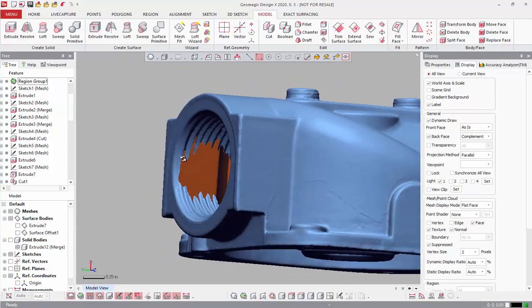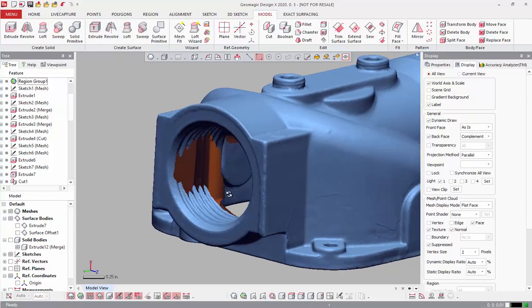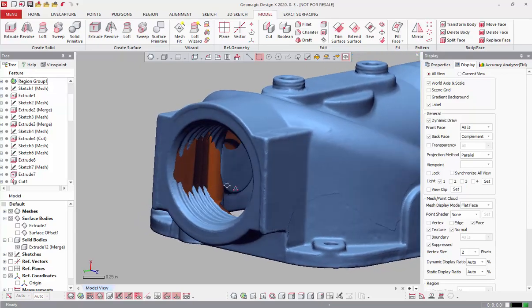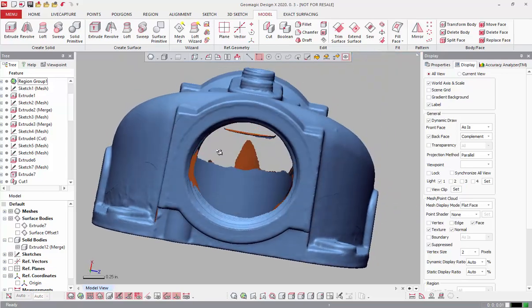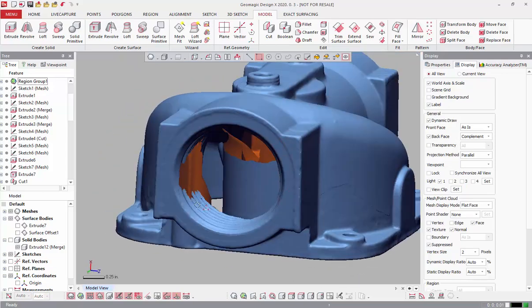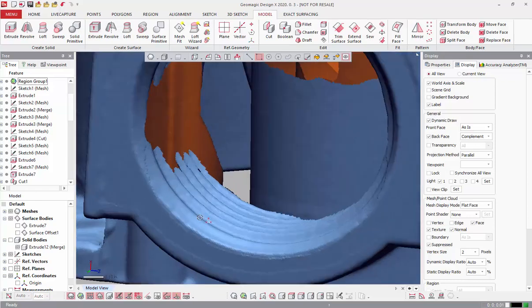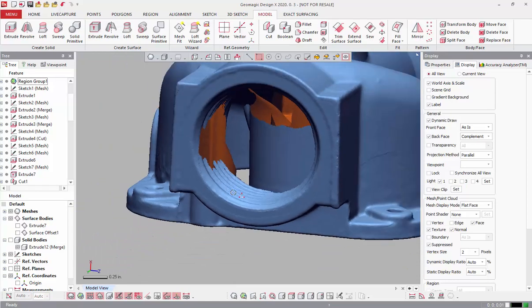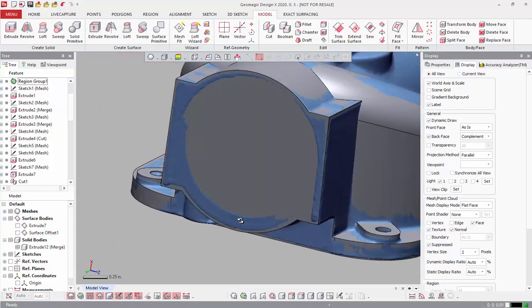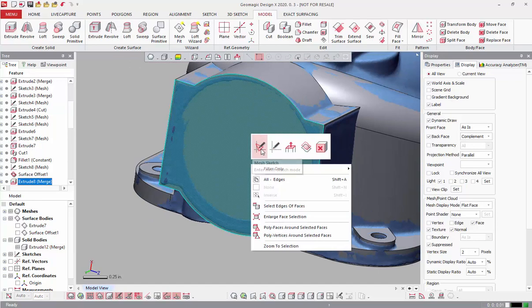One thing that I'll start by doing, obviously, is just cutting the hole out. I'm going to cut the minimum diameter hole, so just at the high point of these threads is what I'm going to use for my sketch for the cylinder that I punch out. I'm going to place that sketch on this face here.